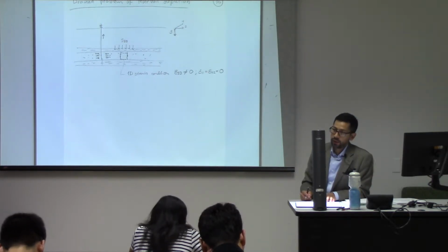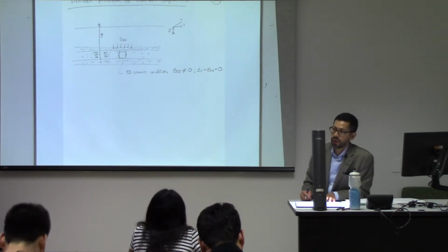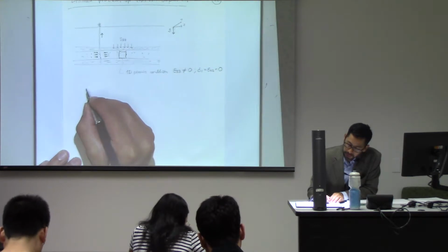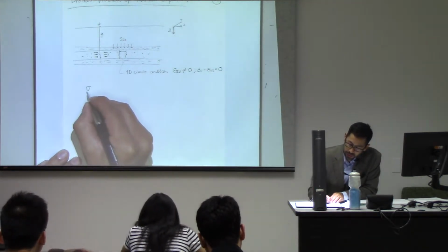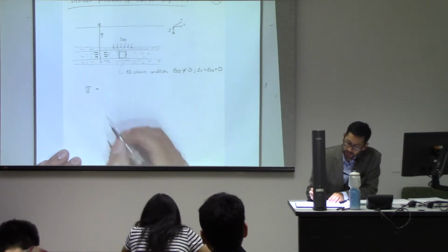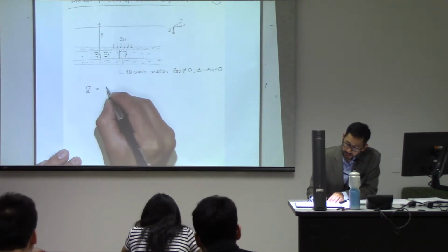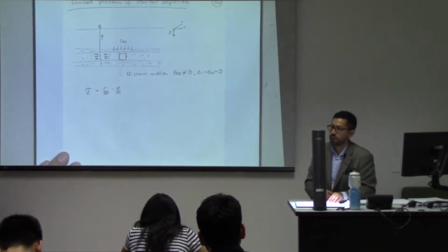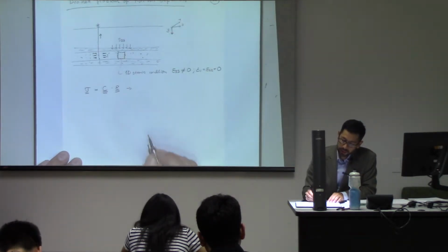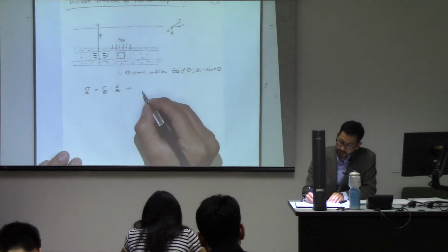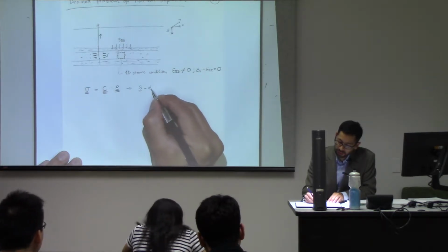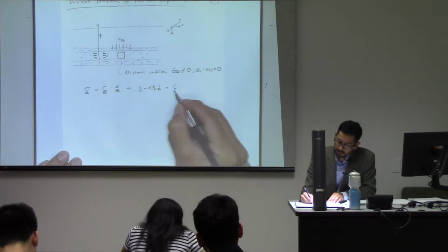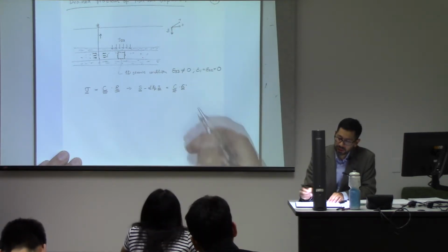Let's try to solve now those variations of stresses with the new equations that we have developed. If you check your notes, we have written that here the effective stress is going to be equal to K, in general the stiffness matrix, times the strain tensor. That's something that we already knew, right? But now we know that this effective stress tensor is actually the total stress tensor minus the Biot coefficient times the pore pressure times the identity matrix, is equal to C times the strain tensor, okay?